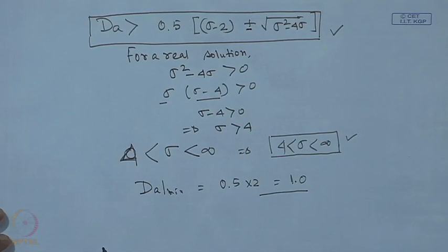So, this is a very interesting and typical application of contraction mapping, and we have seen how contraction mapping can be utilized in the case of an enzyme catalyzed fermentation process, and in order to obtain a unique steady state for this particular system, what conditions on the parameters we have to think of. So, we move to the next illustrative example.